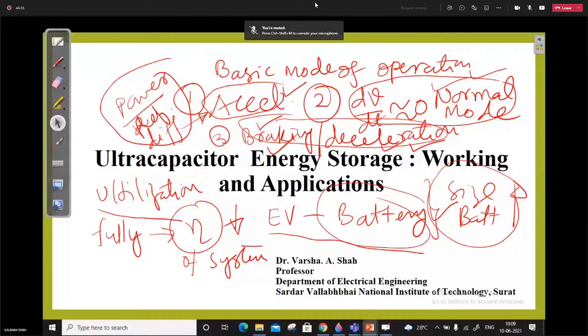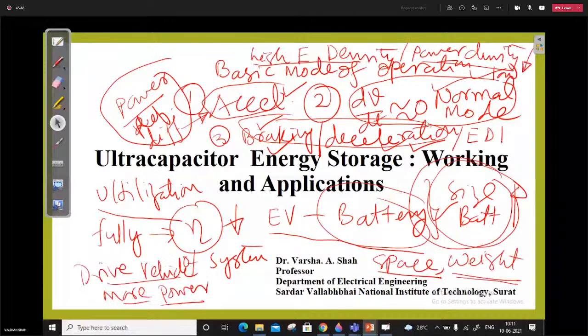So here, if we have a single source, the size of battery will be very, very large. It means it will take more space in the vehicle. We have limitations with space also, because we have to accommodate everything within the available space of the vehicle. And while oversizing your source, the overall efficiency of your EV will greatly reduce.